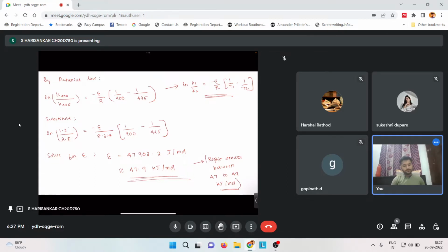Okay, so this is how we solved this question. So what we did, we first found out the epsilons, because this is a gas phase reaction. So we found out the epsilon which is needed to accommodate for the change in volume of this gas phase reaction. So we found the epsilon for both CSTR and PFR. Then we found out the rate constants for CSTR and PFR using their design equations. And once we had the rate constants from the design equations, we substituted those rate constants into the Arrhenius equation, and we just had to solve one equation and find activation energy E.